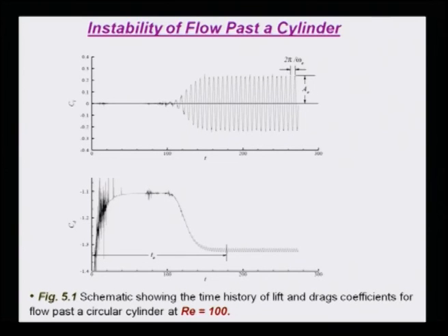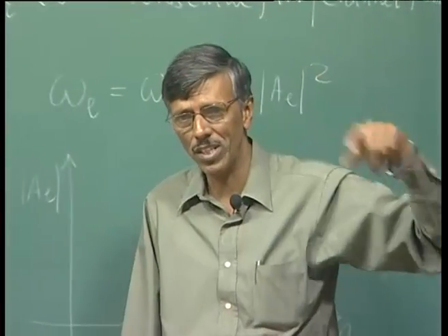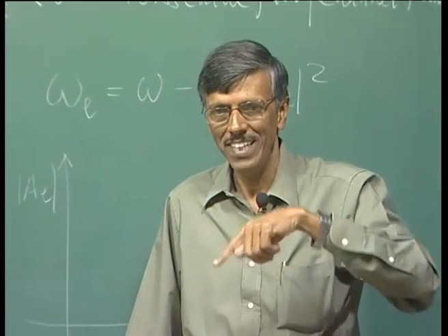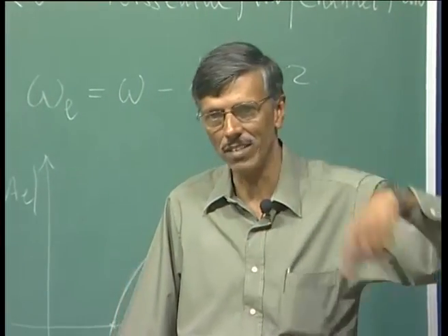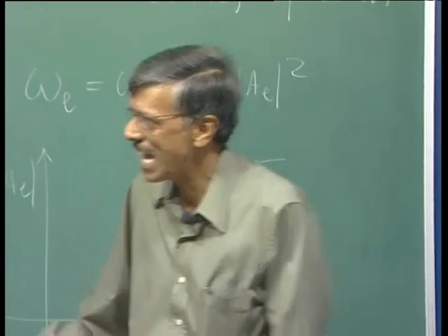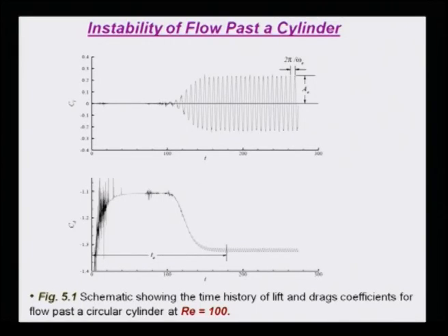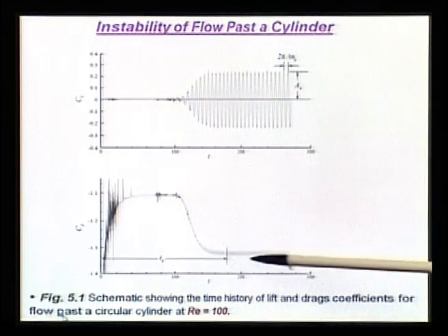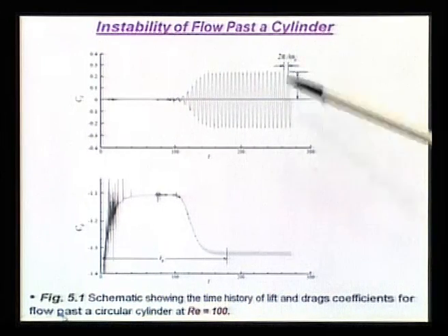So, think about it again. Why would you see that? Because the full cycle gives you one Karman vortex shedding, but in that full cycle also the drag varies about its mean, and so that is why this frequency is twice this frequency.